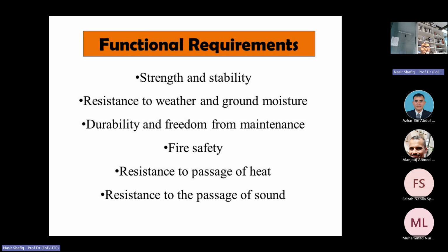When you design a new pipeline, for example a gas pipeline for a maximum allowable operating pressure of 200 bar, and for that API or any standard you design an API 5L X65 steel pipe, the pipeline design is governed by the wall thickness of the pipe, and you come up with a thickness of 20 mm. For example, X65 pipe for 200 bar pressure.